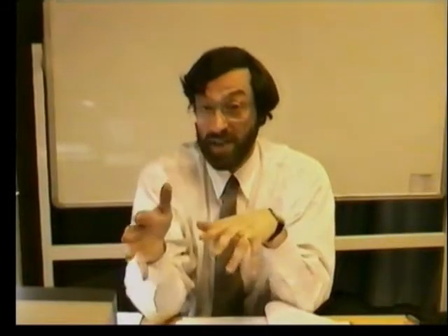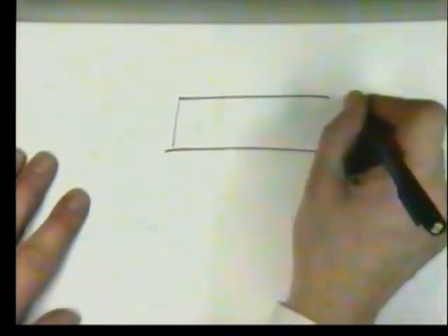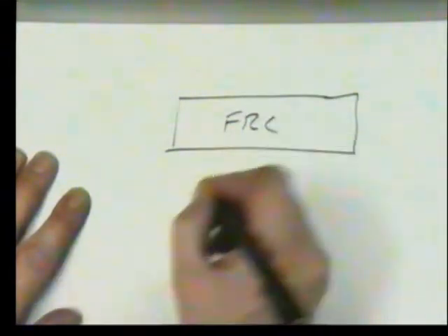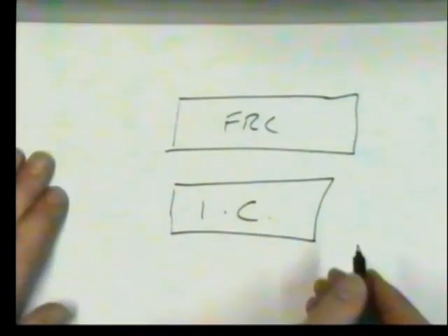But as we'll see later on, if you've got multiple interrupts running, you could have problems with that concept. Because if an interrupt is already being serviced, you can't stop an interrupt to service another interrupt. You must finish the interrupt itself. So, what I've introduced to you instead to overcome this problem is the idea of, if there's our free running counter, the input capture register.